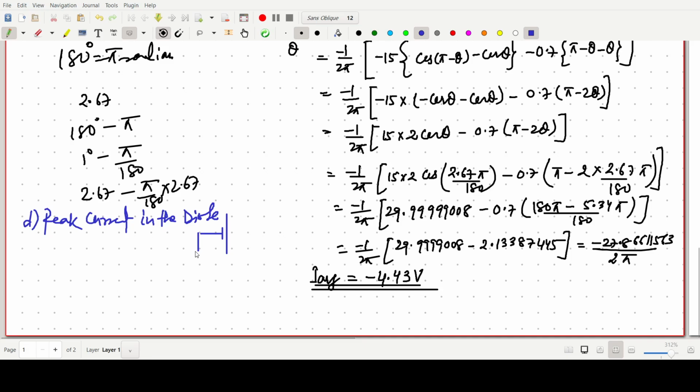At what condition? When we are giving the maximum voltage, make it minus plus. I am writing this as minus 15 volt, and this one will be 0.7 volt. So that will be on, and this one will be the current. R is there. This current is the maximum current, because during that time it is forward biased for this minus 15 volt. So the diode will give maximum current only when this is minus 15 volt.